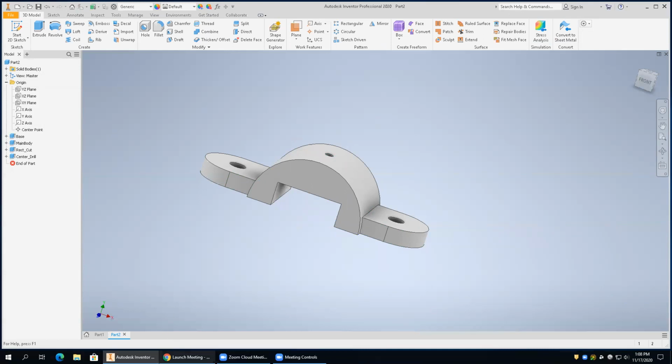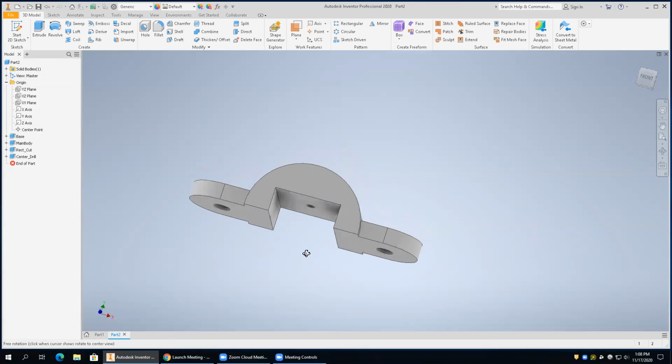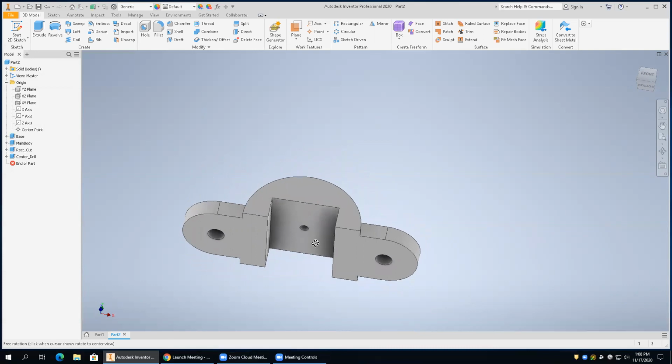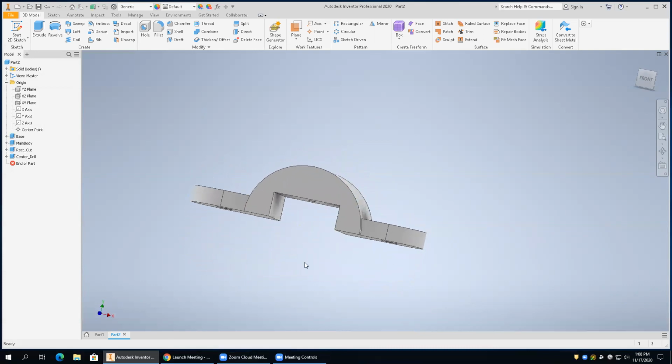And if you go back and look here, you'll notice that the drill hole went with it because the drill hole was linked to that rectangular cut. So if the rectangular cut changed, the drill hole did with it, right? Everybody see that? That's an important concept right there.